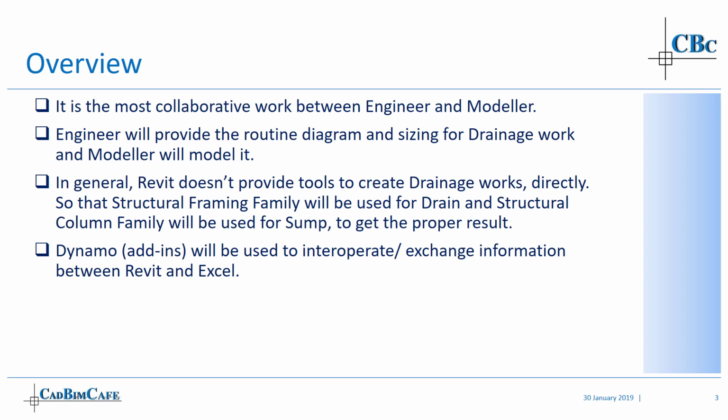So in general, Revit doesn't have the tools to create the drainage works directly. So we have to think of an alternative way to get this done. In this section, I will be using the structural framing family for the drain and the structural column for the sump to get the proper result. Additionally, I will be using the Dynamo add-in to exchange information between Revit and Excel.